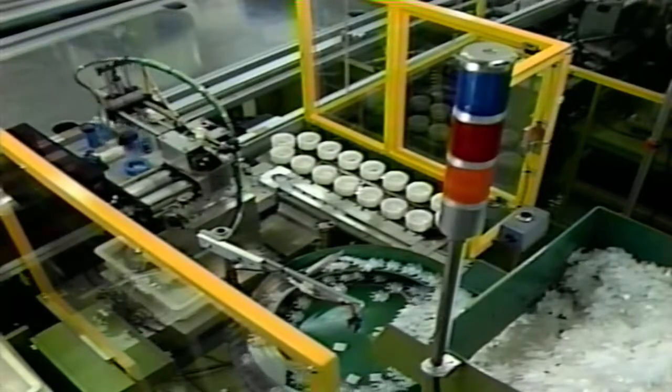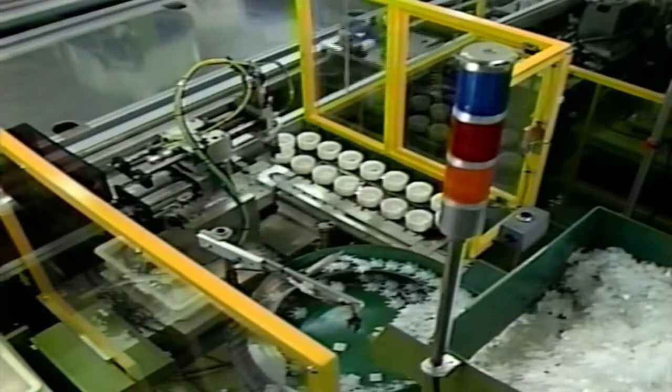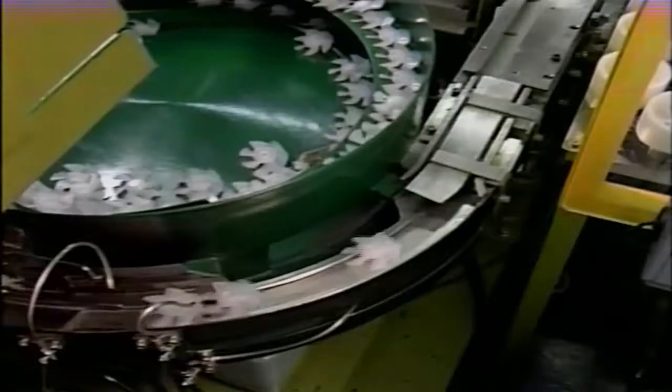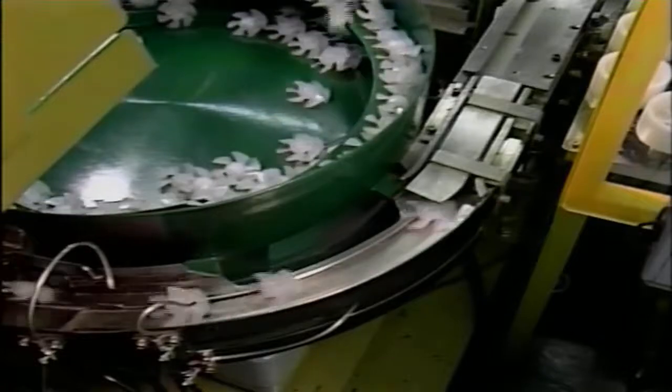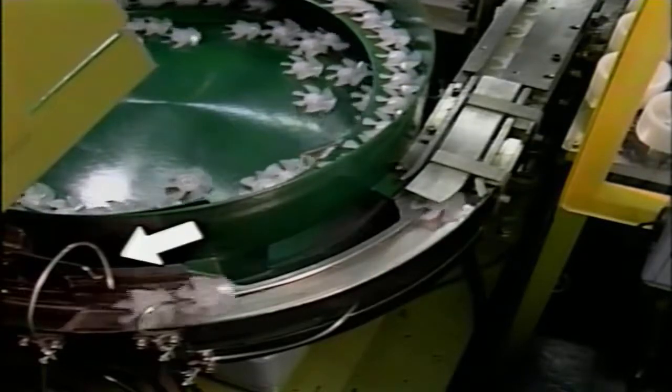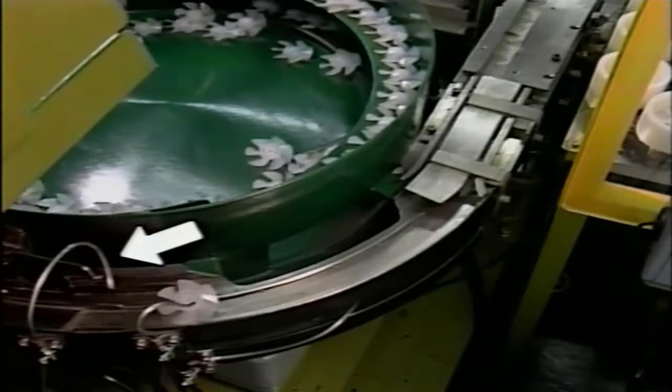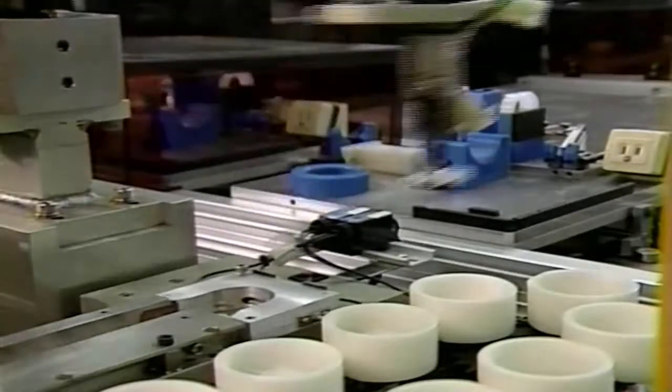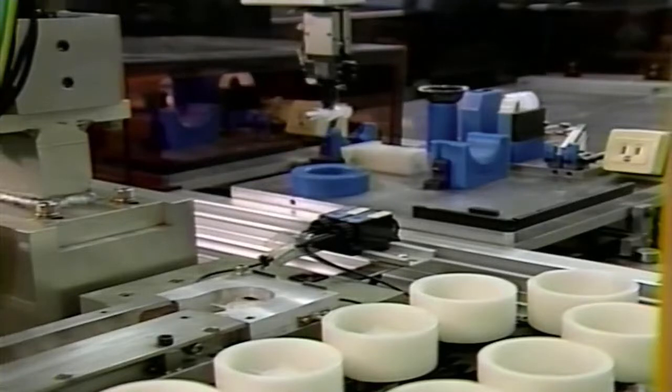Based on the 4 steps of corrective maintenance, the short stoppage we looked at earlier with the parts feeder was successfully solved by installing a nozzle to blow air into the middle of the chute. This serves to separate the parts on the chute and keep the blades from getting tangled together. The result, zero stoppages.